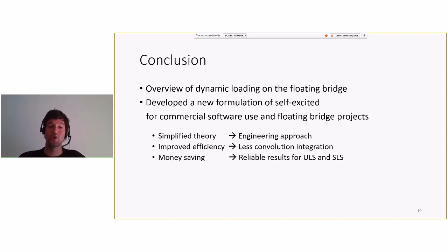We also simplified the theory with simple polynomial fits to flutter derivatives. I think everybody will like to work with that theory much more than with nonlinear regressions. And we have a good efficiency of those algorithms. We think they are efficient enough to be introduced on large scale projects like 5 kilometer long bridges or 10 kilometers or whatever you might build.